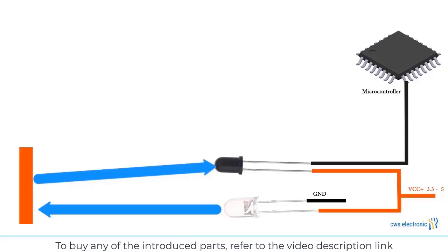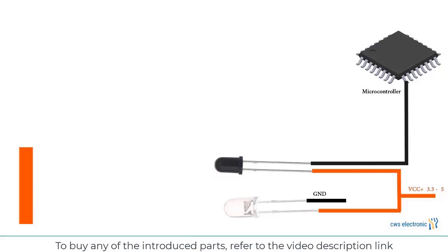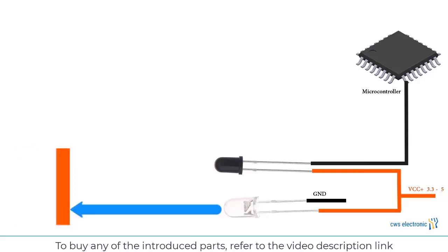In this case, the light that hits the receiver, this phototransistor, starts passing voltage, and this voltage reaches an IC for detection, and thus the IC, as programmed, detects that there is an obstacle in the way. Now, the closer the robot gets to the obstacle, the intensity of the reflected light increases, and the voltage in the receiver increases. And this is how it is determined how close the robot is to the obstacle. So using the sensor, both the presence or absence of the obstacle can be detected, and the proximity of the robot to it.